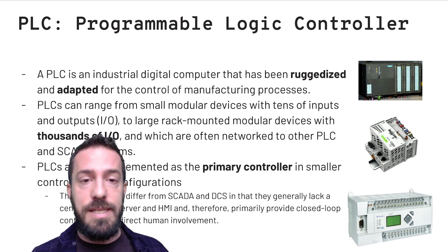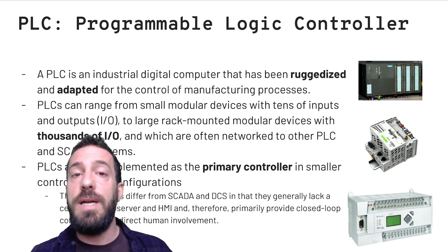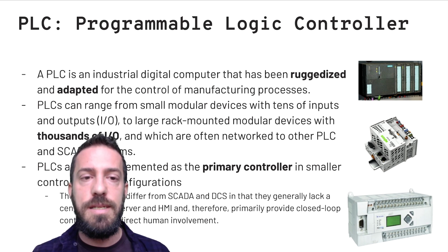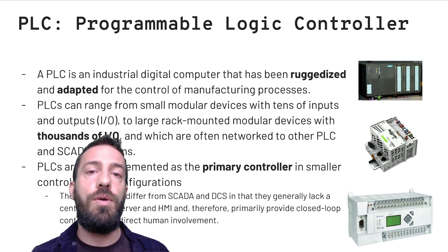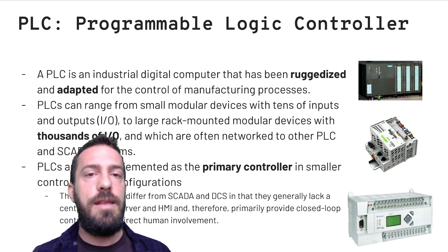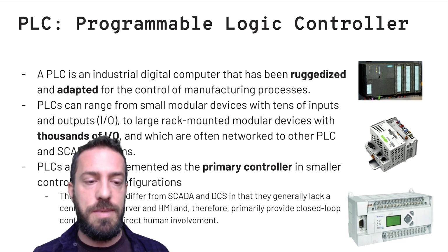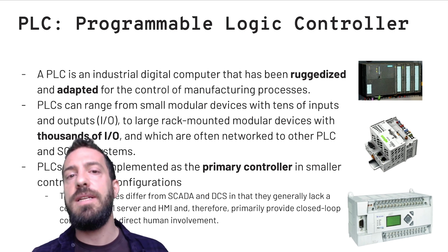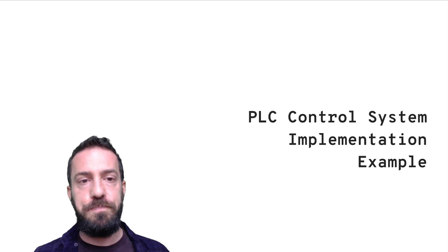A PLC has been designed to respond automatically to process changes, so if it is attacked, while with SCADA the effect could be only providing wrong information to the operators, and the operators may suspect something may be going wrong with the data acquisition systems. So there's also a big difference in thinking about security of SCADA and DCS compared to PLC.